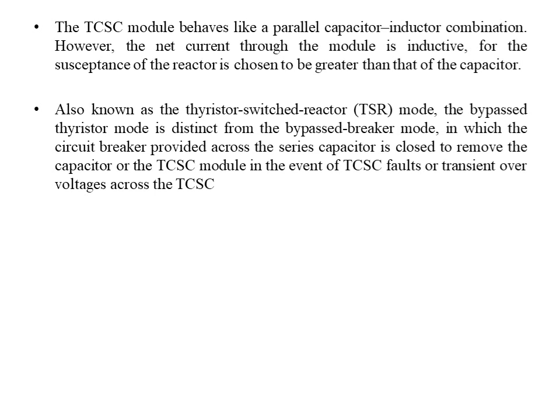So the point to be concluded in this bypass mode is that whatever current will flow is mainly dependent upon the conduction angle applied across the thyristor valve. That is, when we apply the firing angle to the thyristor valve and it goes into conducting mode, the current will flow through this parallel thyristor valve to the load. That means the current flowing in the line will be highly inductive in nature.